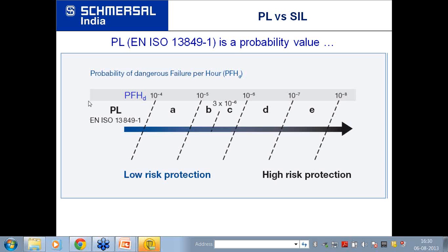Mr. Pratap Singh from DCM Textiles Hisar is saying sometimes the PLC hangs in normal running condition. What could be the possible causes? Now this is again a software error, and one of the causes, as we have seen in our case study, is that you will not get an output and the machine may not stop when you want it to stop. And that is why a PLC is not a safe device. It is not a proven component.